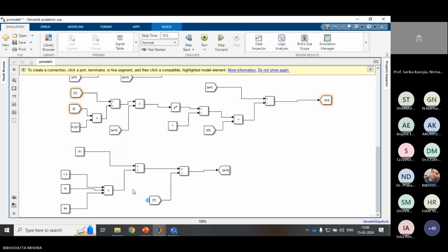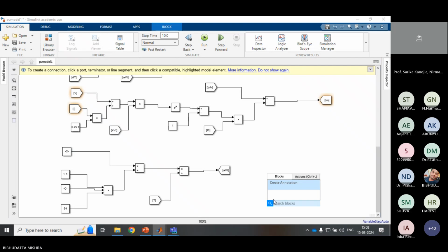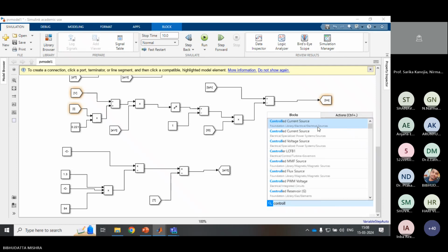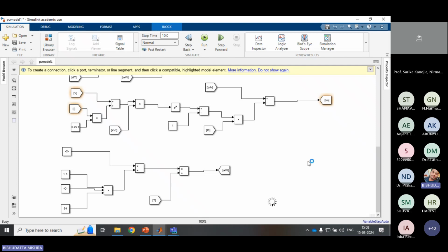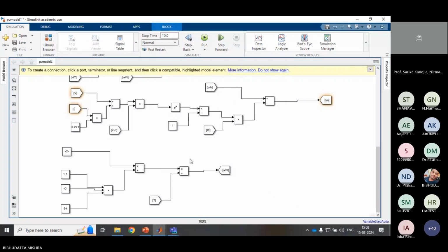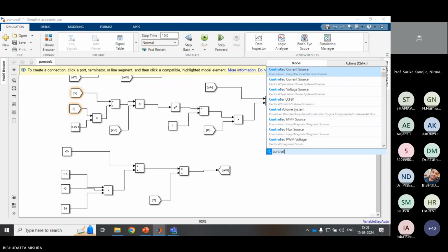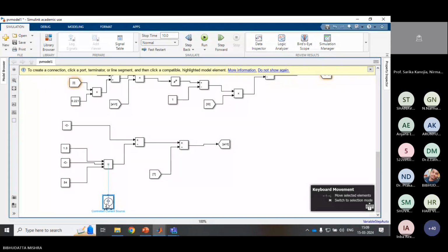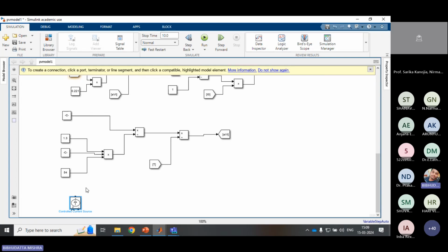Right now the circuit total, the PV circuit will do, where the controlled current source, that IM acts as a controlled current source. A shunt resistance is required, which is RSH, and a series resistance RS. The values are also given.